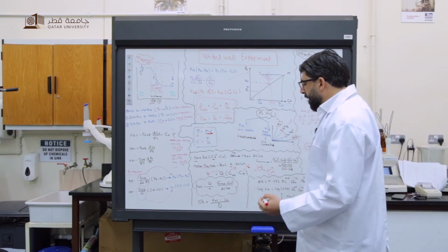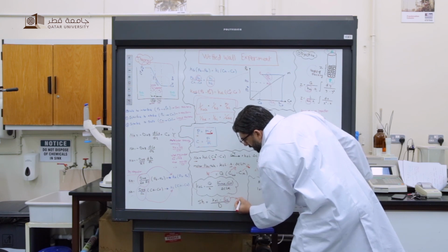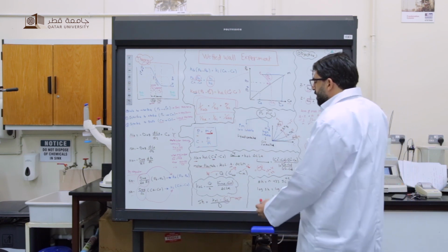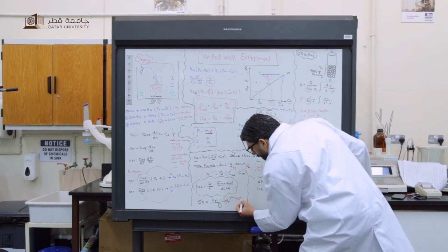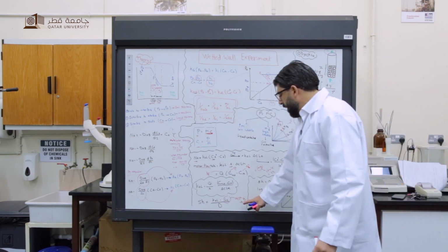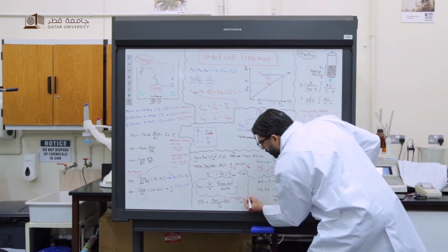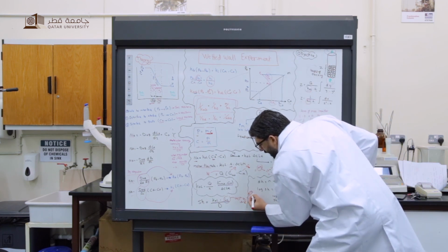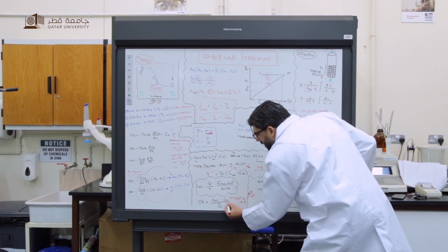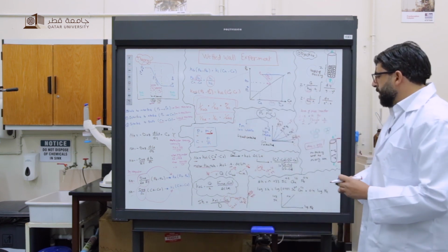So again, we have to find the hydraulic diameter. The hydraulic diameter here is 4 times area over P, where A is the flow area and P is the wetted perimeter. So it will be equal to 4 πδL over πd, so both will be cancelled. Finally, the characteristic length will be 4 times L, the height of the column.